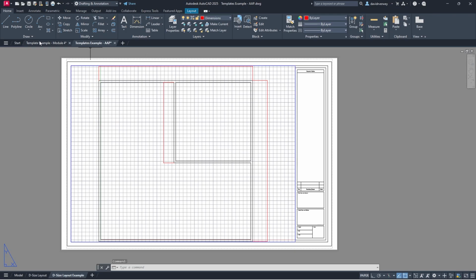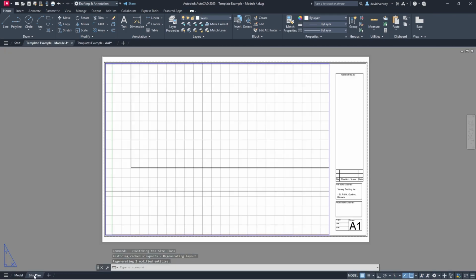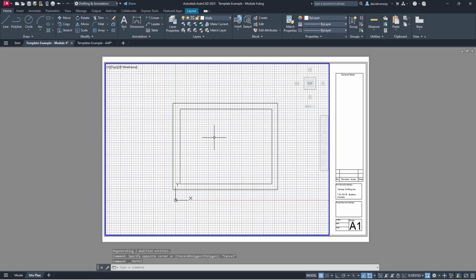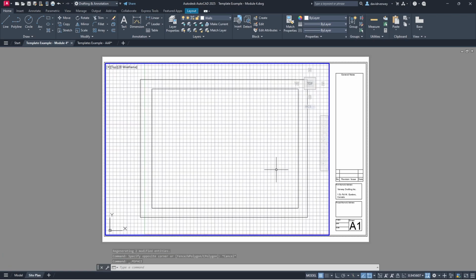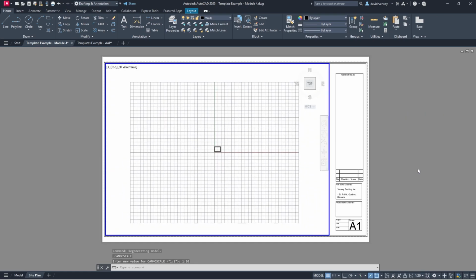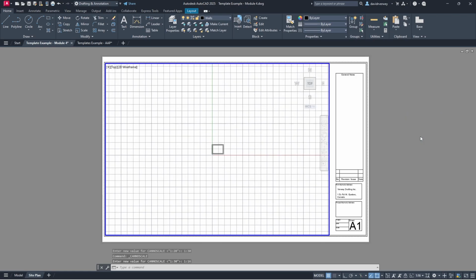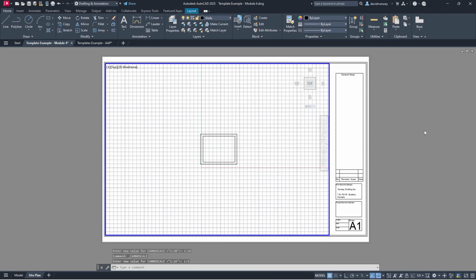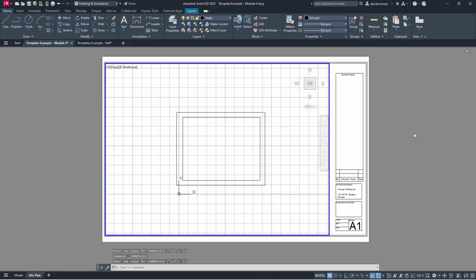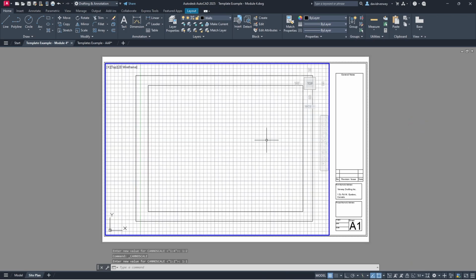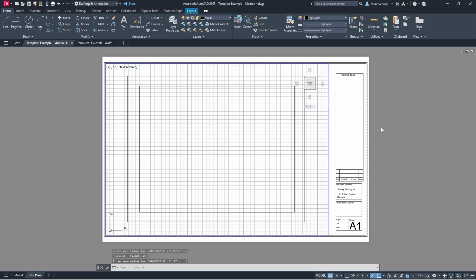And we can go in here to our main drawing and give it a scale. You can see we have our drawing here. Then we're going to select our scale, and you want to select a scale that encompasses your drawing and makes it look nice. So we'll go 1/8, quarter, half. We could probably go 1 to 1. There we go. We'll go 1 to 1 and then lock it, and there you go. Once this is done, put in your notes, your revision numbers, your project name and address, and that's how you do that.